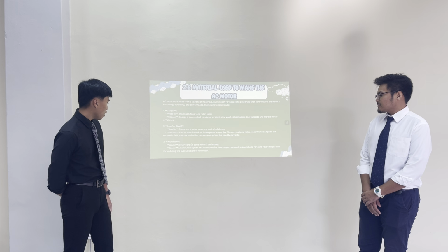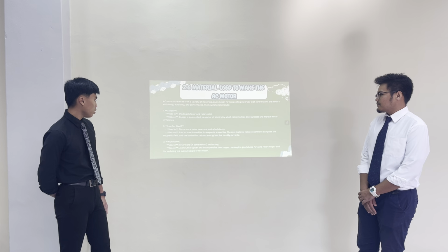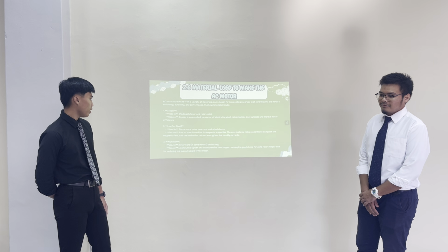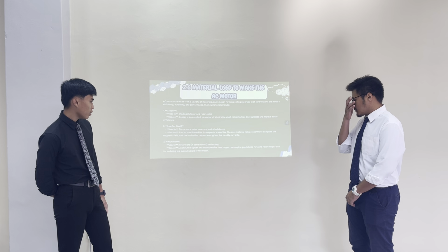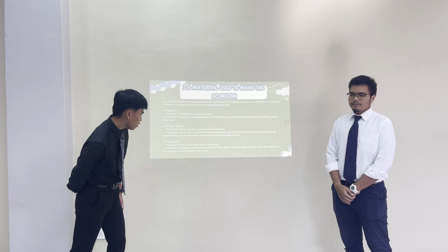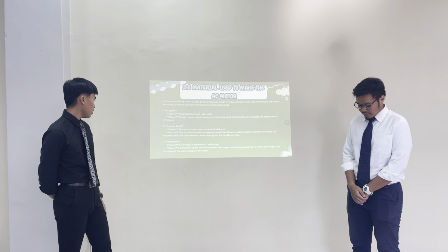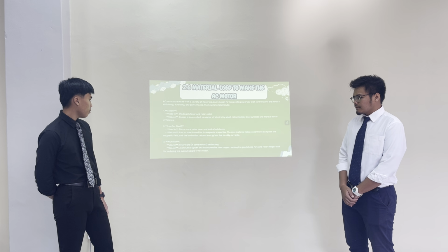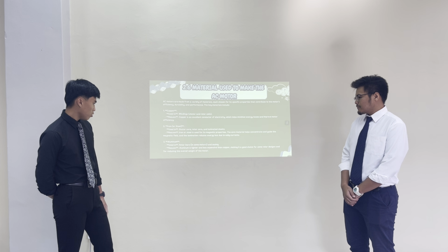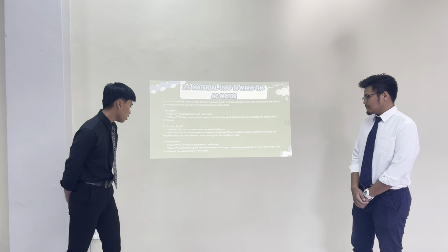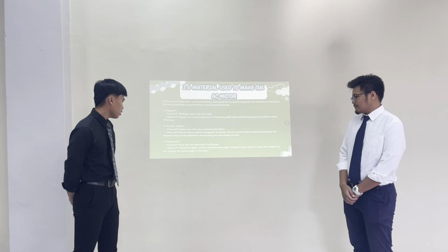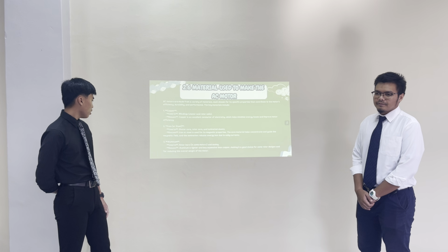Reason: iron or steel is used for its magnetic properties. The core materials help contain and guide the magnetic field, and the lamination reduces energy loss due to eddy current. 3.